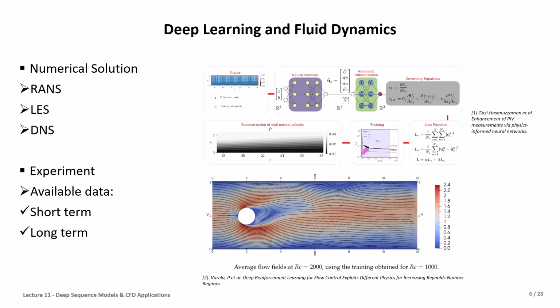Then we had the numerical approach, which for turbulent flow uses Reynolds-averaged Navier-Stokes (RANS), large eddy simulation (LES), and direct numerical simulation (DNS). We talked about the differences and the advantages and disadvantages of these methods, and especially in the HPC course, we emphasized the computing power required to run LES and DNS, which are costly in contrast to RANS.